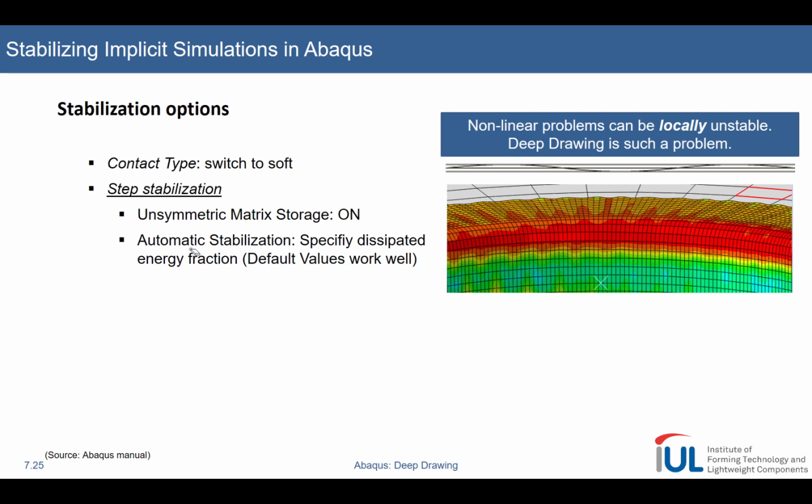Remember, we talked about the 4 different approaches to define our blank holder modeling, and for the simulations you're seeing here right now, I've chosen a fixed gap for the distance between my blank holder and my die of 1 mm. And my sheet thickness was 0.8 mm.